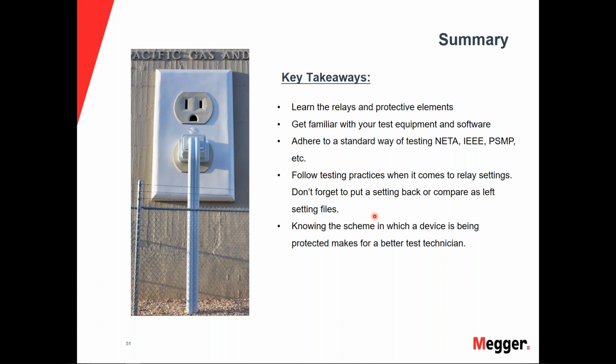If you are doing some type of microprocessor-based relay or something that has software to it, then pull those settings out as found. Pull those settings out, keep those settings on your PC or close to you, and that way whenever you get done testing, you can put those settings back in the relay and run a compare function. You want to make sure that you always compare the relay before you walk off, because you're the actual last one to ever touch it, and those fingers get pointed at you if something happens. And also, it's just kind of a little bit of knowing the scheme.